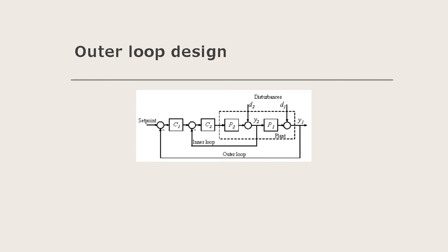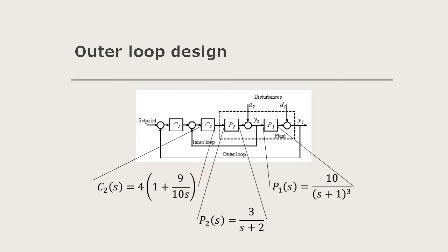So then, in order to analyze, we need to consider that the heater system can be modeled by the diagram shown, that the transfer function of the plants have been already determined, and that the inner loop controller C2 has already been designed. In consequence, we need to just design the outer controller. Firstly, we implement the blocks inside the red rectangle in MATLAB. In this way, we will be considering this part of the system as a new plant and subject it to a step experiment in order to observe its response.